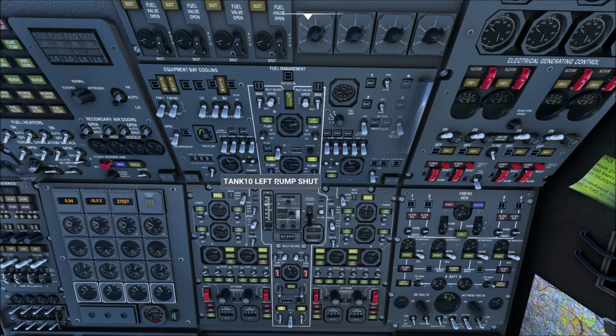You are able to also move fuel from these tanks into these tanks. Again, same process really, just opening valves, telling the fuel where you want it to go to keep moving stuff further back. And eventually, when you're at maximum Mach, you want a COG balance of 59.